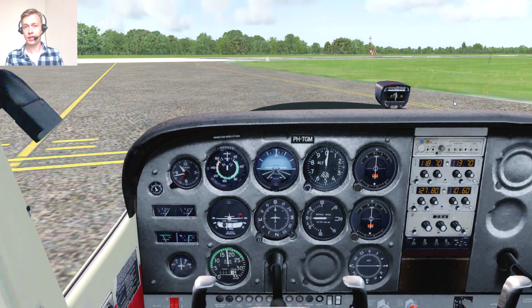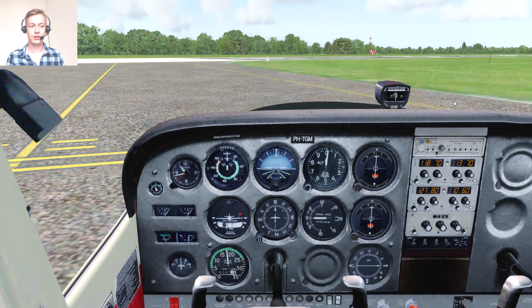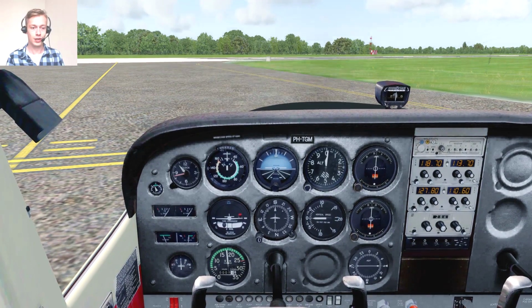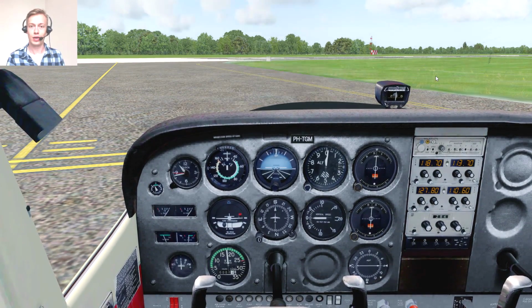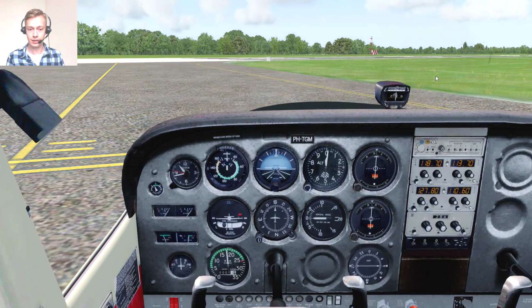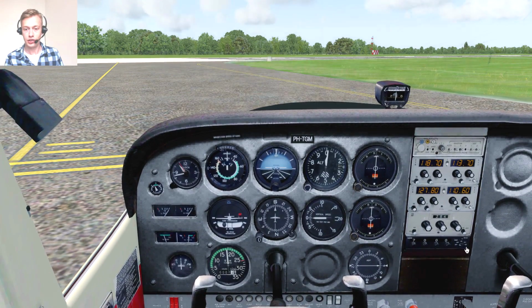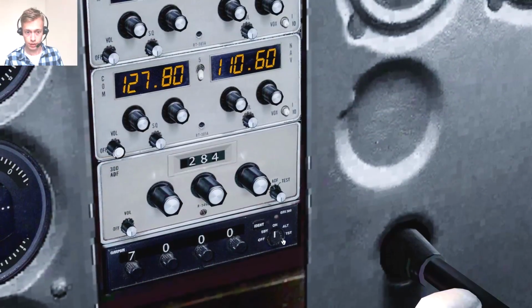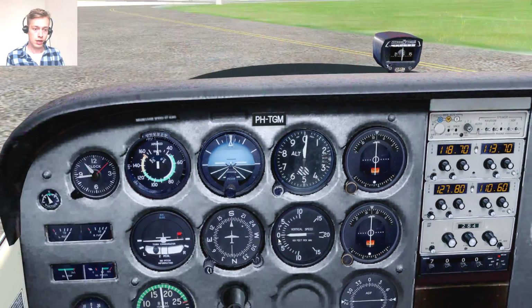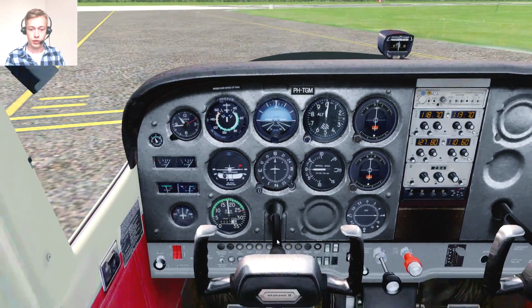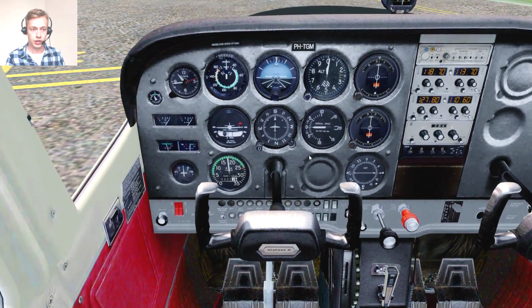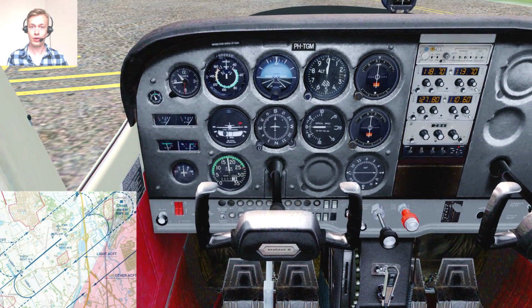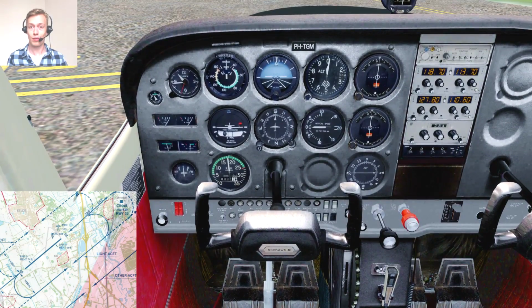So just be aware that the air traffic controller takes this into account, that you need this time. And then when you're done, you can report ready for departure. Just make sure that all the indications are in the green, and then you're good to go. Alright. One thing that you want to make sure right at this stage is also to turn on the transponder. Make sure it's to the active mode. There we go. It's on, as you can see. And we'll just turn on our landing lights as well at this stage. And of course, make sure that you have your VFR chart at the ready of the circuit, and then we can report ready for departure.